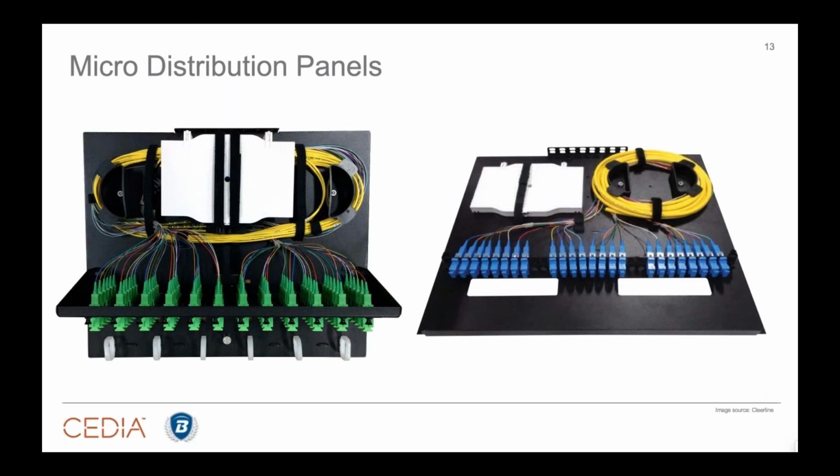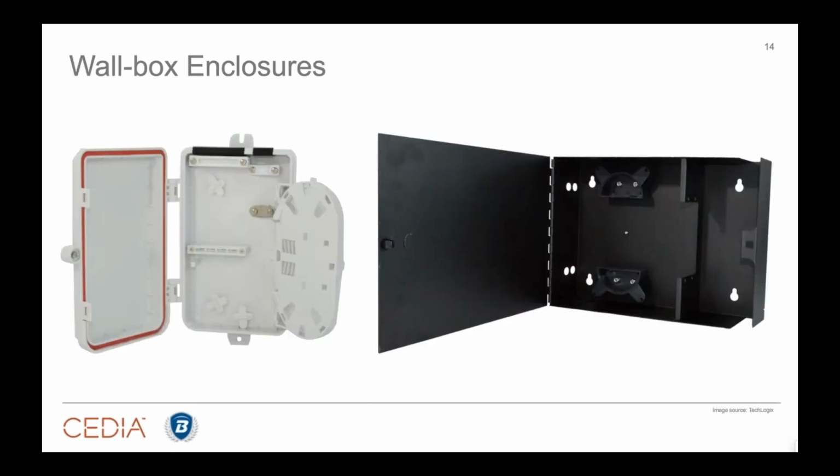And you can always tell a fiber optic enclosure because it has a couple of components to it. It has a coiler, right, for service loops and to manage your excess fiber optic cable. It manages breaking open that jacket, unzipping it, taking those individual strands out, and sending them to the individual coupling points, the connectors, the splice points, right? This is what fiber optic equipment does. Whether you get a rack tray or a wall box, you can always tell it's for fiber because those strands are managed. Even plastic outdoor demarc boxes have these components built in so you can manage these strands. It's a very common part of the fiber optic conversation, and I encourage you to incorporate them into your design. They're really not that expensive.